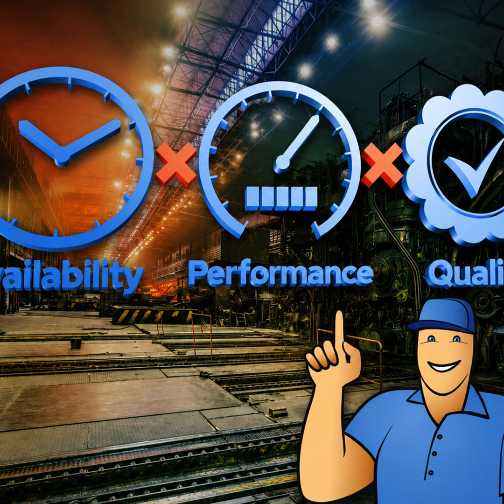If your OEE score is 60 to 75%, recover the hidden losses. If you're looking at these values, chances are you've gotten your equipment issues fixed and are ready to tackle the hidden losses. Minor stops are the order of the day here. For example, maybe you see brief jams that are cleared quickly before moving on. 8 stops times 30 seconds could be 4 minutes of lost time per shift. Over the course of a year, that comes up to 13 hours of lost manufacturing productivity, multiplied by the number of workstations where this is happening.